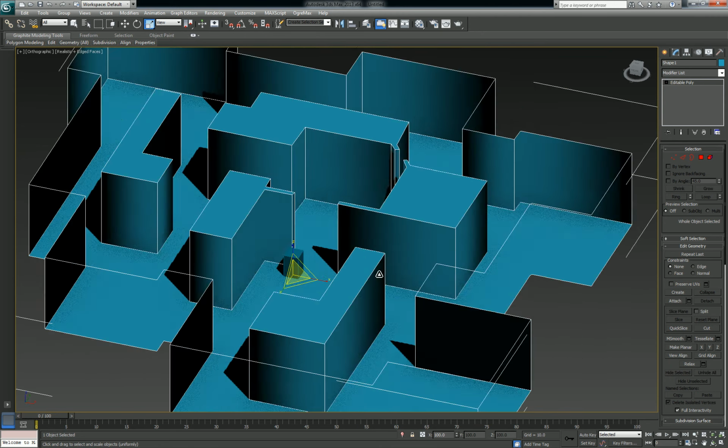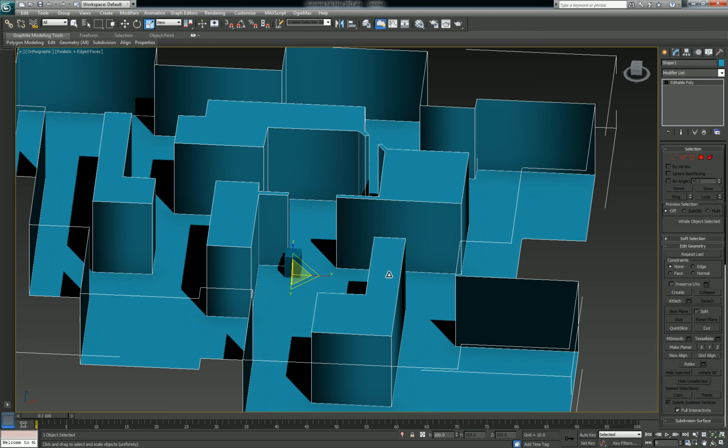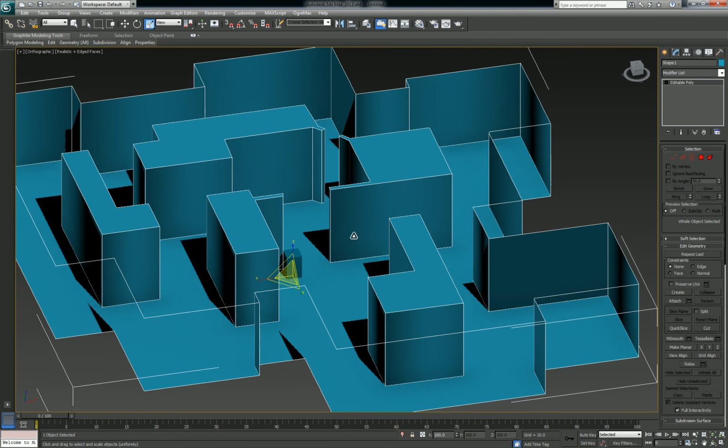Now this is pretty critical, and you should constantly be on guard for it, because you can inadvertently, for example, if you want to connect a doorknob to a building, and the doorknob's relative scale is not equal to the relative scale of the building, your building is now going to become the size of the doorknob as far as the engine is concerned. So, be aware that if you do notice that something in your scene has disappeared, 9 times out of 10 it's because your scaling is off.